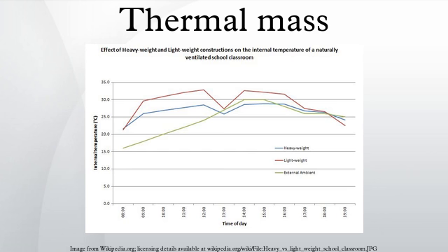Thermal mass for limiting summertime overheating: thermal mass is ideally placed within a building where it is shielded from direct solar gain but exposed to the building occupants. It is therefore most commonly associated with solid concrete floor slabs in naturally ventilated or low-energy mechanically ventilated buildings where the concrete soffit is left exposed to the occupied space.